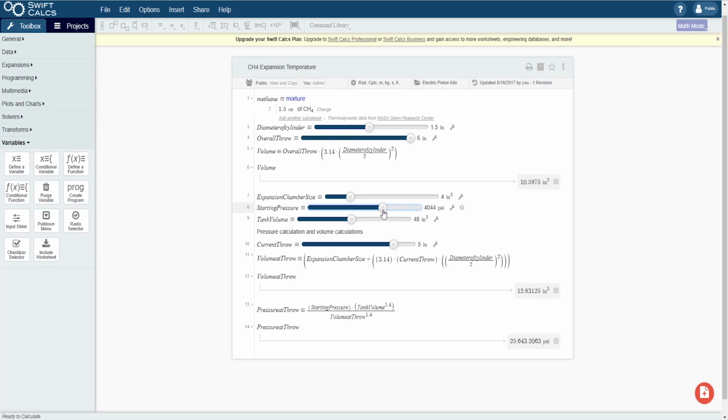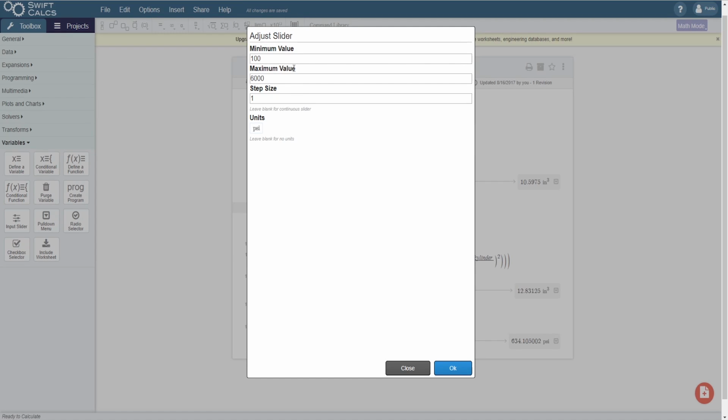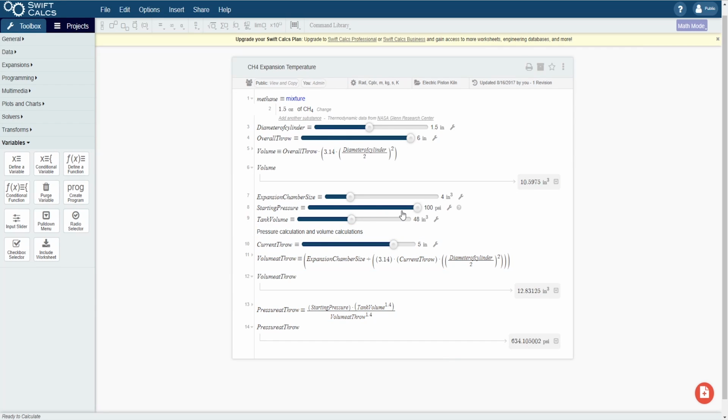That's our standard pressure, so let's drop this down until we start to see something that we could actually work with. It's 500 psi at maximum. You don't even work with power tools at 500 psi, because that's a large tank volume going to a very small volume.